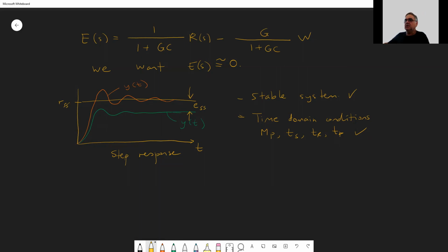If you have a car, you want it to go at 90 kilometers per hour. It makes a jump, and eventually it reaches 80 kilometers per hour, but not 90 kilometers. That means that there is a steady state error of 10 kilometers per hour. Or you want your robot arm, the robot arm example, remember, to rotate 90 degrees, but it can only rotate 85 degrees, so there is 5 degrees of steady state error.